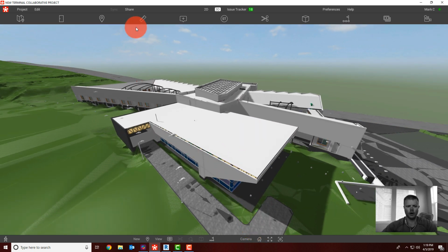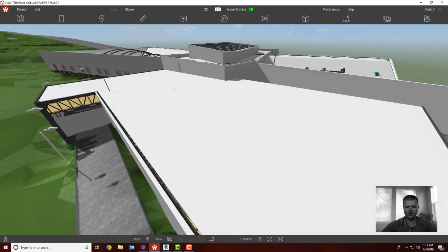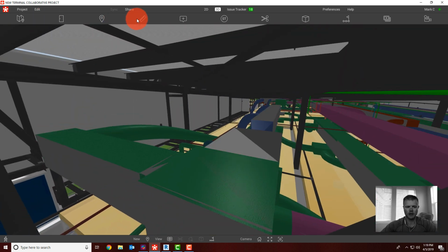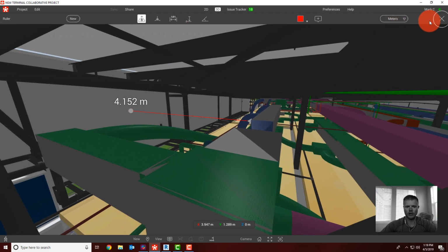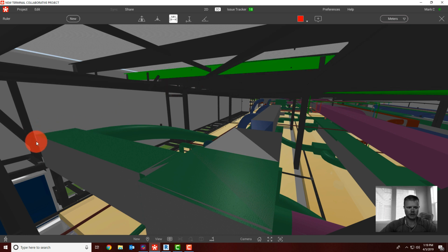And we're going to go through our measuring button next. So again, very simple to be able to pull dimensions here. Just grab this measuring tool. We can calculate the specific elevation just by dragging this. We can select a specific distance between different objects. And then we can change based on what we'd like to see, so feet, millimeters, etc. We can also check minimum distances as well. So we'll just grab our minimum distance, grab one object, grab another object, and it's going to calculate the minimum distance between those two Revit families.